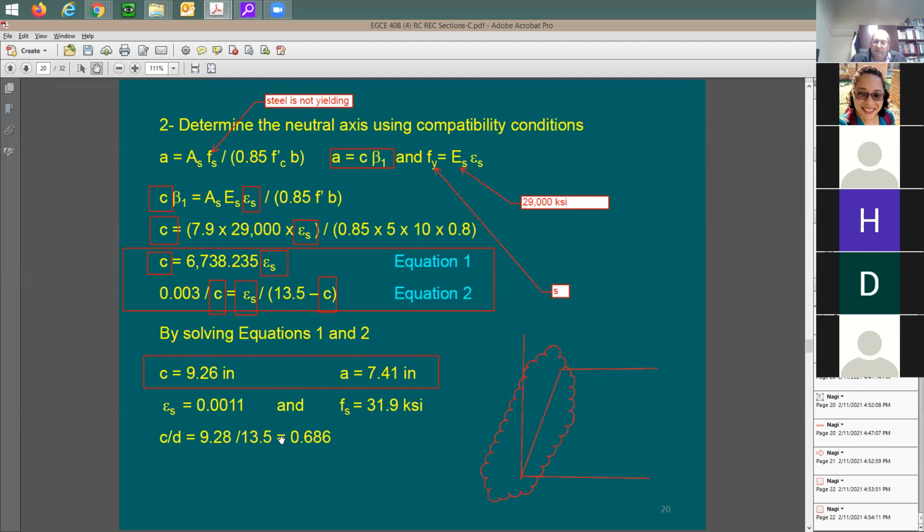Not just to dump the reinforcing and say, now let's get care of it. You cannot say, for example, for 3 rebars, the strength is 120. When I put 9 rebars, without knowing all of these facts, you're going to say the strength is going to be maybe 360. Why? Because I tripled the amount of rebars and I'm expecting the strength to be tripled, but it didn't happen this way. You just gained 10% additional strength. Any questions?